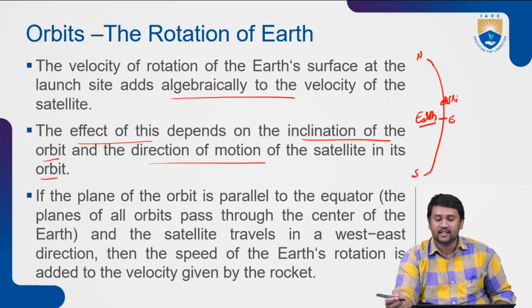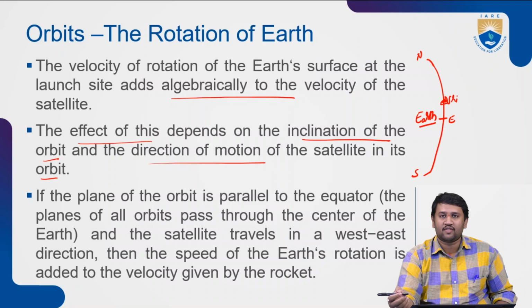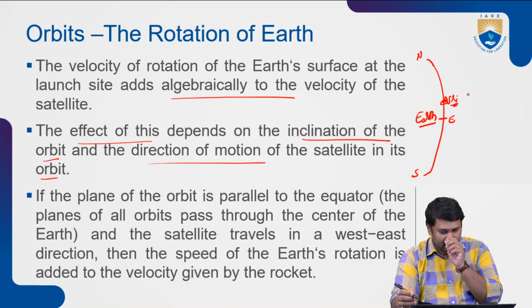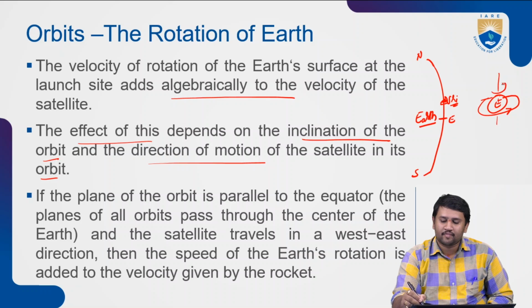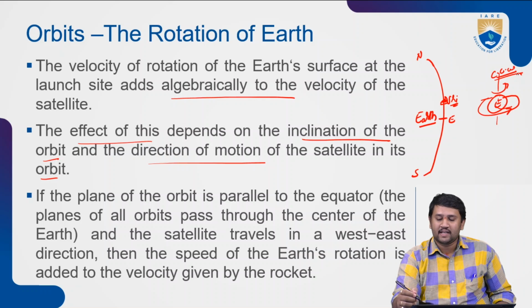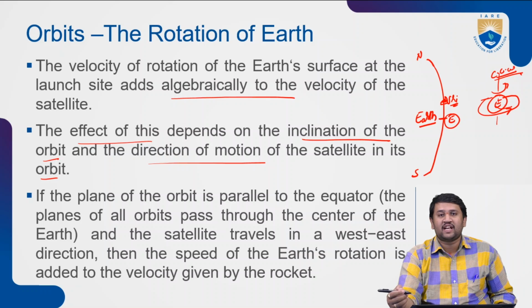Now, as we know, in any sphere, the circumferential point is the best point to transfer the velocity of the Earth. So coming to Sriharikota, whenever you are launching a satellite from Sriharikota, if the orbit is related to your Earth's rotation, or geosynchronous, whatever you feel like, right? Now, if the Earth is rotating in a counterclockwise direction, and we are launching our rockets in the same counterclockwise direction at some altitude at the equator, right? What happens? It adds a significant amount of the Earth's rotational velocity also.